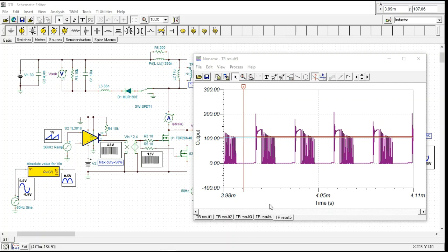But in this case, our leakage inductance is sitting at a fairly low level, percentage-wise it's only a couple of percent. Depending on how badly you wind the transformer, that could easily have been double this. And if you go to double this, trust me, these spikes go way up. They go way up. So this overall is a good design.